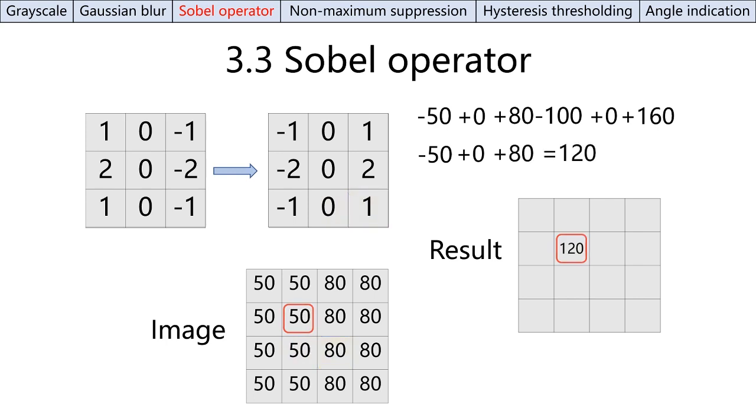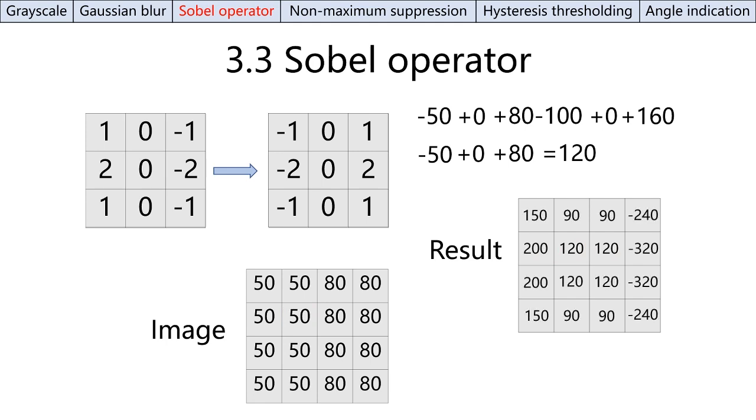After doing that, looking at the output image, the difference values between pixels are enlarged. In some cases, the values will be negative because they indicate the direction of the luminance gradient. If we want to display the output, we need to convert them into the range 0 to 255.